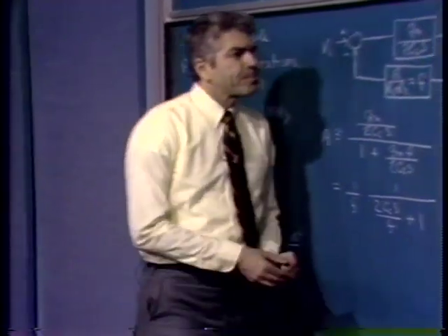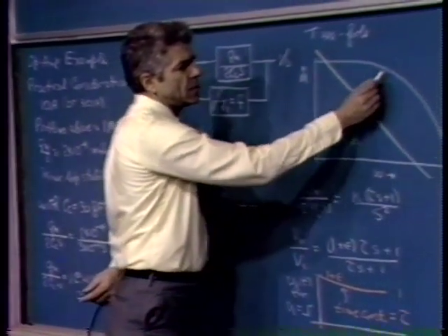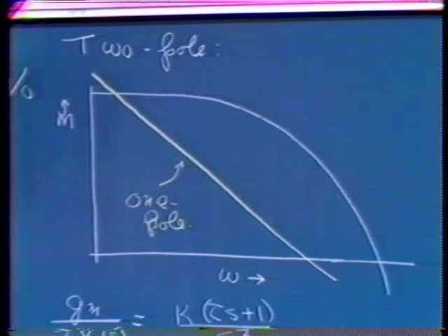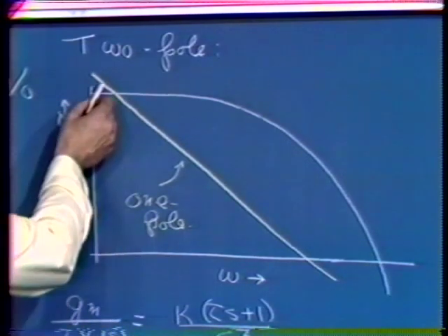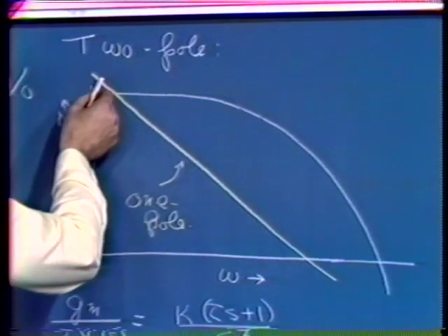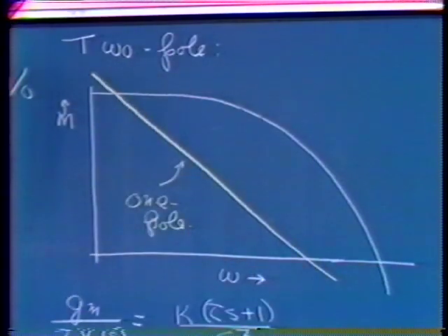Let's suppose that this is the open loop transfer function of the amplifier without compensation when we consider the effects of loading by the compensating network. In general, the loading of the compensating network usually doesn't change that curve much. So let's suppose somehow we know that this is the uncompensated open loop transfer function for the amplifier. If we use single pole compensation and possibly adjust it for unity gain at a megahertz or something like that, this is the approximating function.